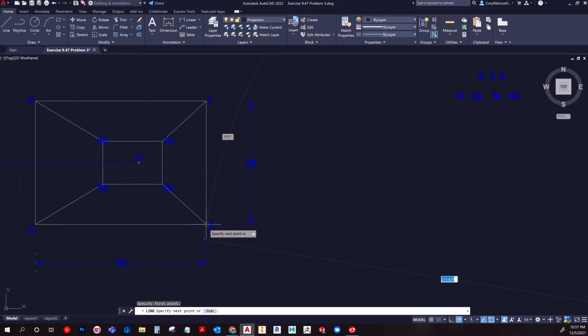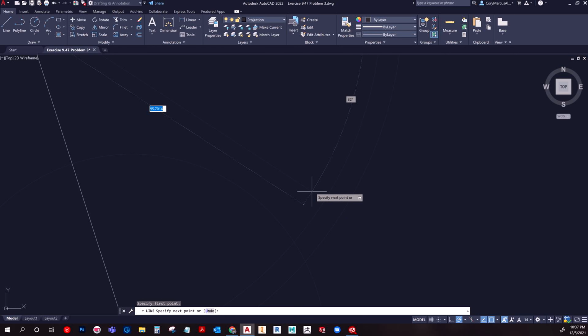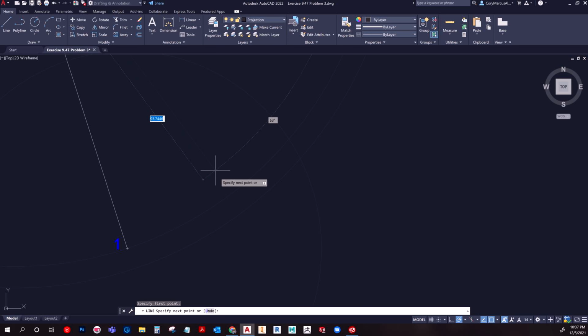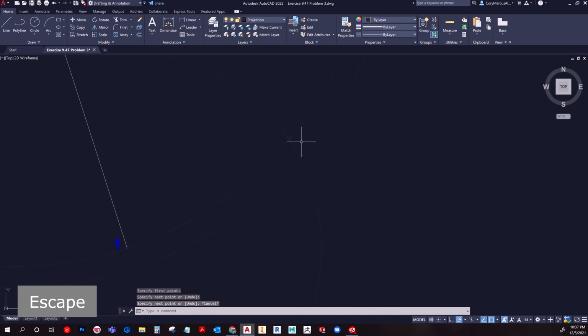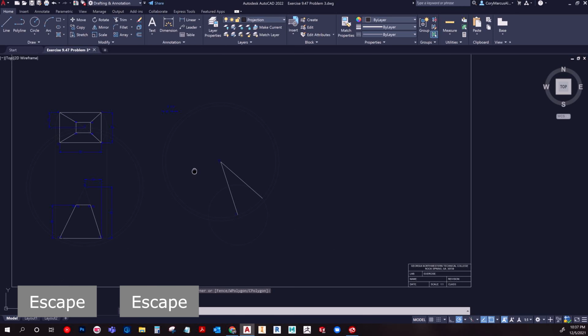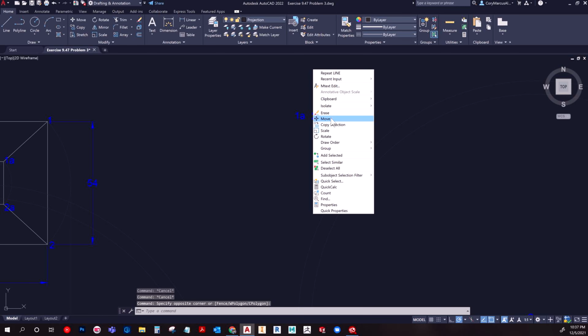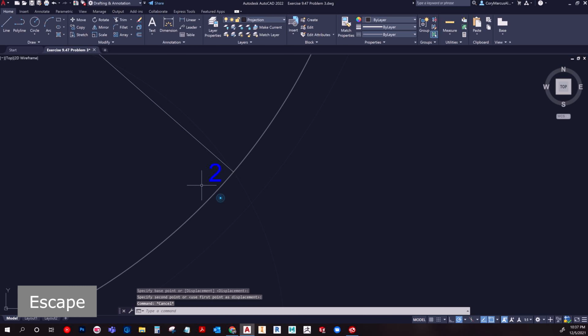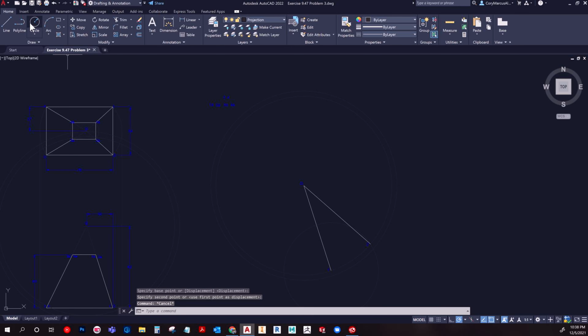So now we're going to edge 2. Now edge 2, as you can see, is the same circle, which is the interior circle. So when you're looking at the crossing, essentially you're choosing, and I'm going to turn my intersection back on, you're going to go for the inner one, not the outer. And again, be very cautious with intersection. I would double check everything because it's so easy to mess these up. And okay, so now we're going to move 2. And you could probably already start to see a trend. It's really not hard. It's just connecting the dots and discerning what goes where.